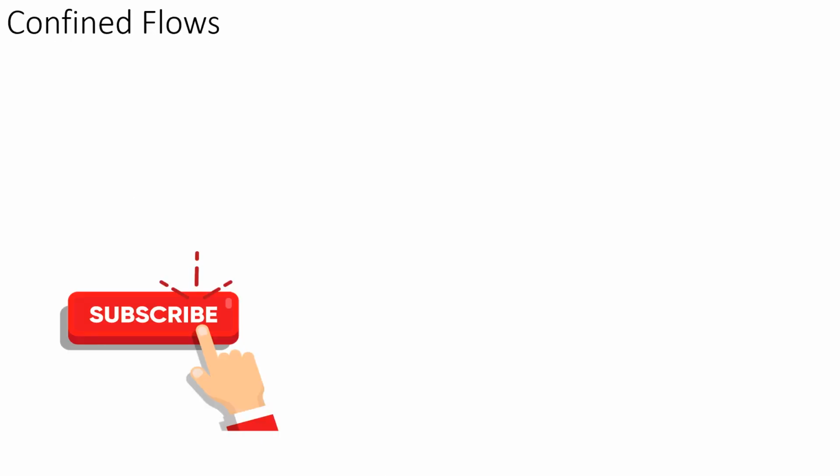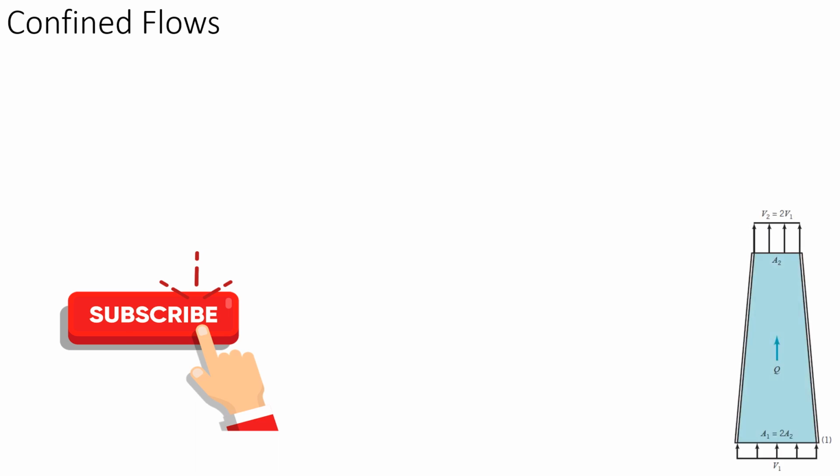Next up is confined flow. Confined flows are those flows in which the fluid is not exposed to the atmosphere. It moves throughout in a confined pipe, meaning a closed channel, and the fluid circulates inside that closed channel. Depending on the geometry of the channel, the fluid velocity and pressure might change. To compute the velocity and the pressure change, we again use the same Bernoulli equation. This is a closed channel.